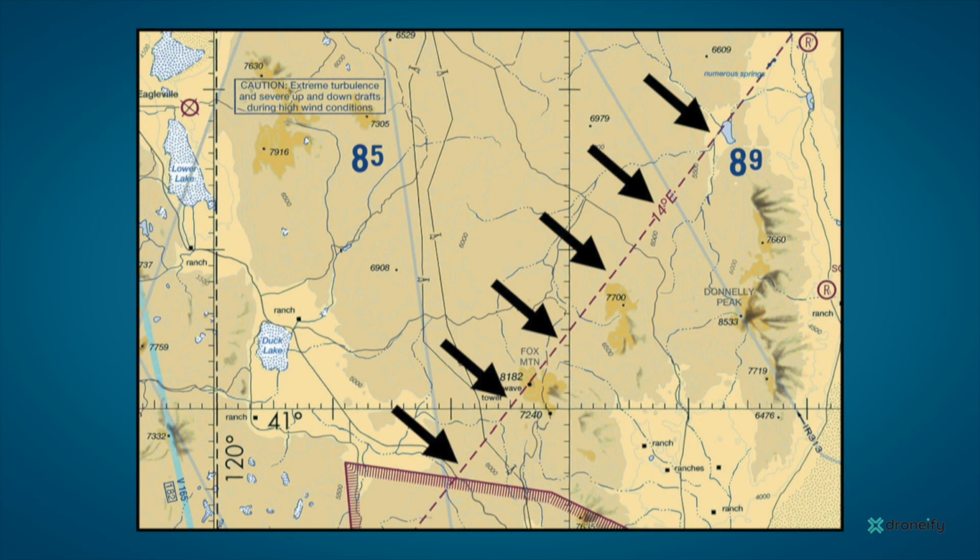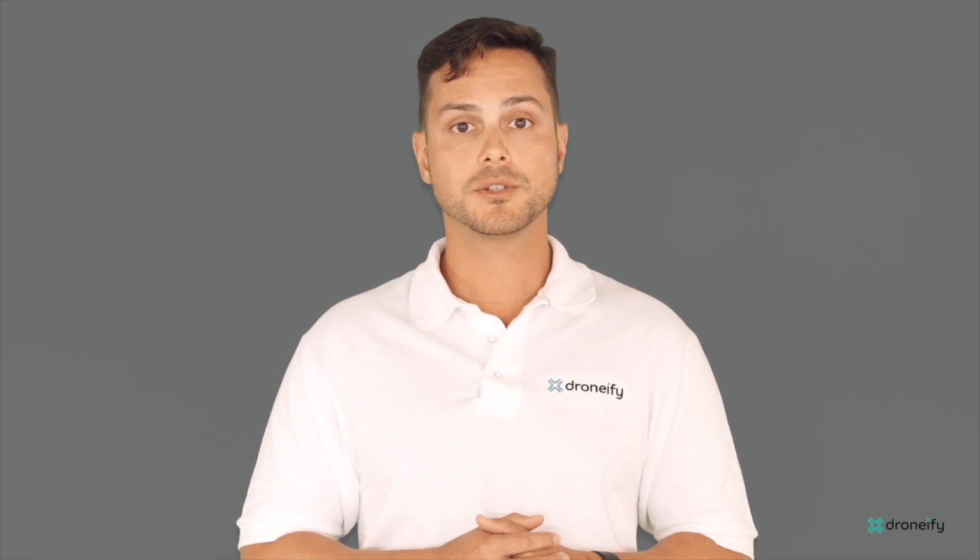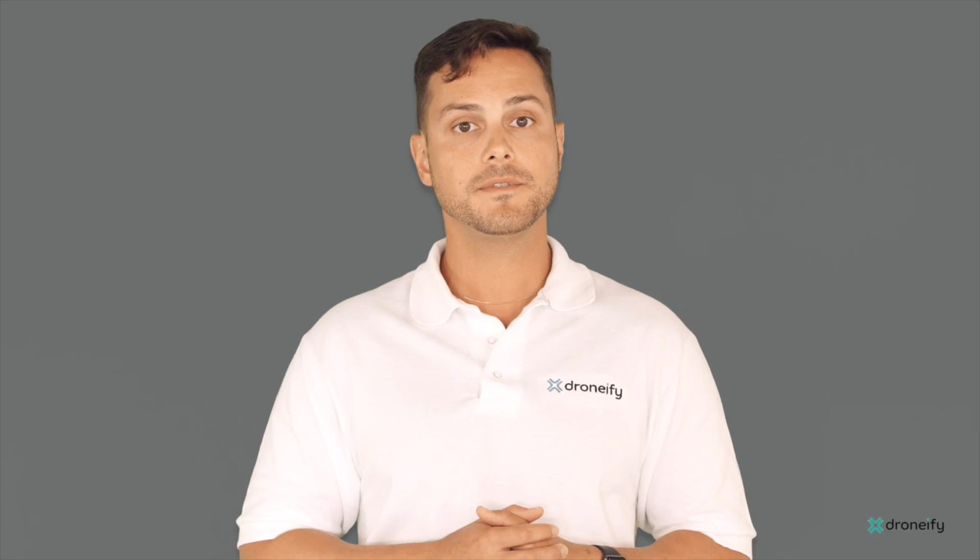When using a magnetic compass for navigation, it is important to adjust for magnetic variation in order to ensure that the compass points in the correct direction. This adjustment is made by adding or subtracting the appropriate number of degrees of magnetic variation to the compass heading. Isogonic lines are used to determine the correct amount of variation to apply based on the location on the chart. Drone pilots must be familiar with the isogonic lines on sectional charts in order to ensure accurate navigation with a magnetic compass. They must also be able to adjust for magnetic variation and maintain situational awareness in the airspace in order to avoid conflicts with other aircraft and maintain safe operations.